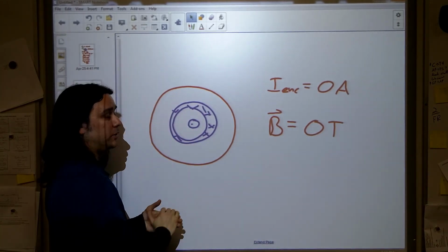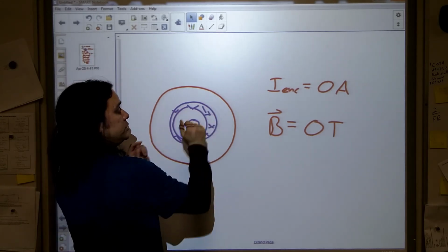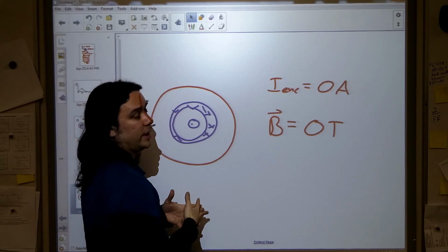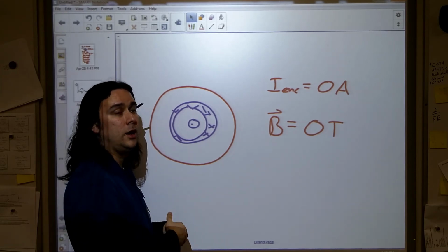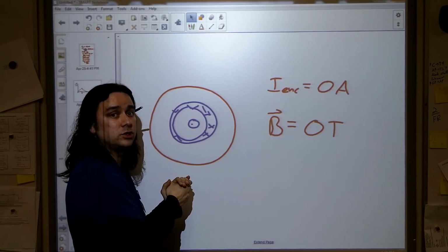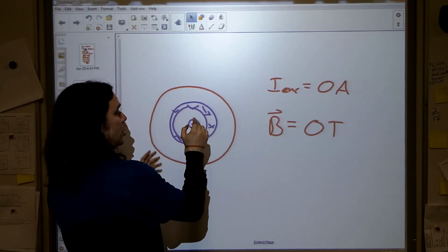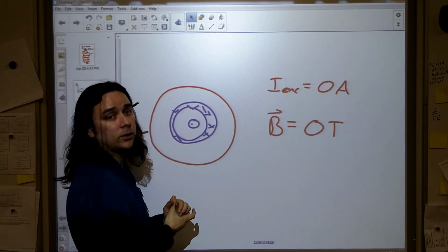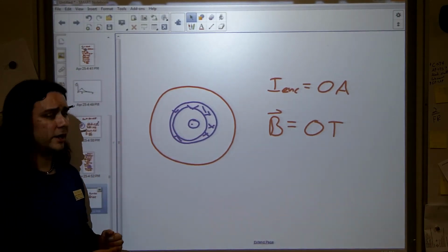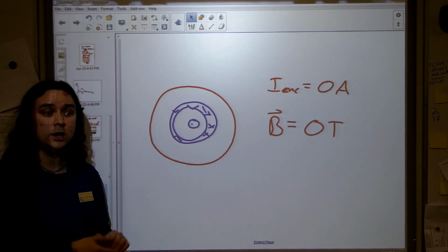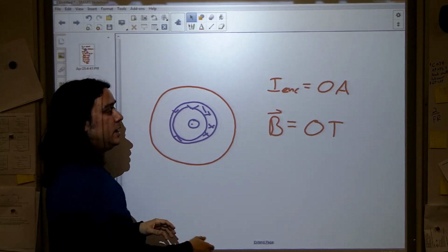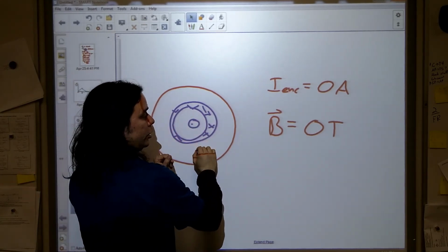If you have a slight difference in how much current is coming out versus how much goes in, you will end up with a net magnetic field, and that will actually trip it and kill the circuit because charges are going somewhere they're not supposed to. We want all of the charges that go into the house to come back out of the house. And if you drop, say, an electrical device in a bathtub or something like that, charges will leave through the water and not come back out the far end of the circuit, giving you a difference in your currents,